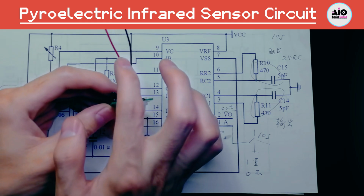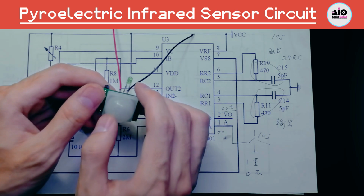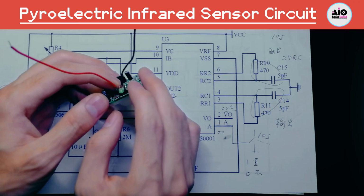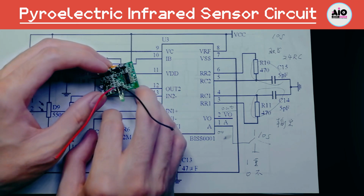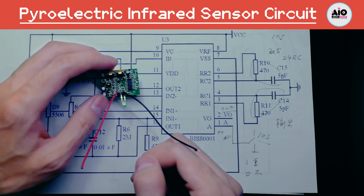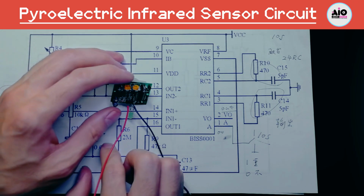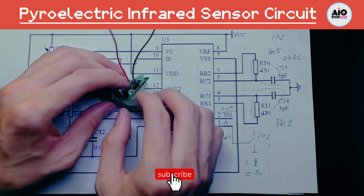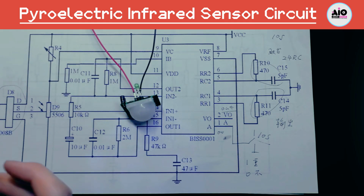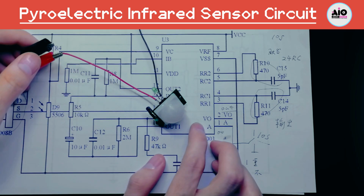Next, let's briefly demonstrate its work. There are 3 pins on the back of it. These 3 pins correspond to the positive pole of the power supply, the negative pole of the power supply, and the output. Since its working current is relatively small, there is no additional amplification part. If you need to drive a load with a larger current or a higher voltage, you need to add an amplification part, such as a transistor amplifier, or drive electrical appliances through a relay to control higher voltage or current loads.